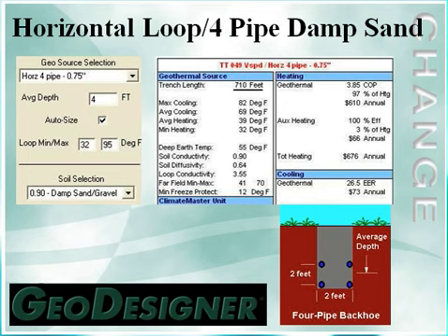When we do backfill, we want to make sure we don't have sharp rocks or objects that might damage the pipe down the road. Also, when we talk about average depth, one of the inputs we did in the loop design portion, I need to know the average depth of those two pipes. Typically we go at 5 foot with the bottom, 3 feet with the return pipe, so my average depth would be 4. However, I do like to stay below the frost line in the local region. As I go to some of the northern markets, we may be at an 8 foot or 10 foot depth. I do just want to caution you, if we're going to deeper than 5 feet, we want to shore up the sides of the trench or cut the tops in at an angle that if some of the soil were to cave into the trench, we don't have any concerns there.